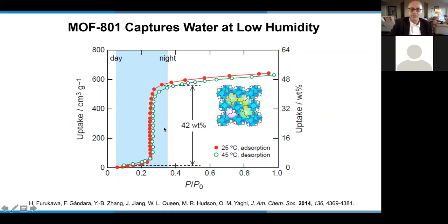And this is the behavior that you see in red, a very sharp knee behavior, which is the power of the isotherm that I have emphasized in my last lecture, is that this shape gives you a lot of information about what's happening in the material, but also the sharper this step is, the higher your working capacity and the lower energy you'll need, because now I only need to vary the conditions very slightly in terms of the humidity to be able to harvest the water. Or I could use, in this case, and another very surprising behavior, is that we are able to extract the water out by heating to 45 degrees C. Okay, now I looked at this uptake and release behavior.